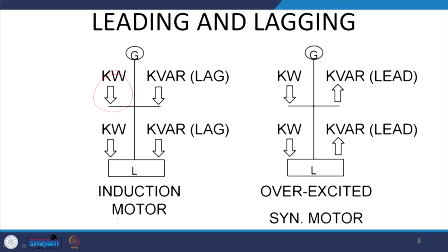So, this is the kilowatt, and ultimately if you have to generate the lagging power factor, that is the kilowatt and the kilowatt hour you will fit. But instead of that, you can have an over-excited synchronous generator, with kilowatt and kVA coming in this direction, leading. But the problem is that you operate by mechanical power, and real power is wasted by this synchronous generator so that it generates the capacitive VAR. Instead of that, why can't we have a static device to generate the capacitive VAR?